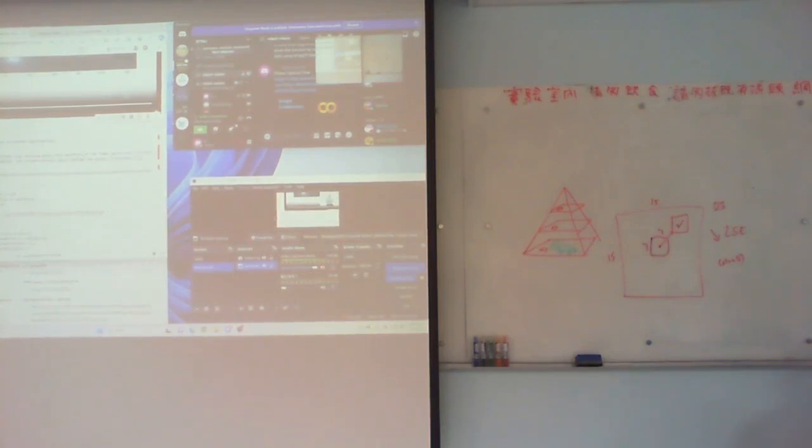You can also do sanity checks. If it's a moving robot and that point just moved 100 kilometers per hour, if it just jumped hundreds of pixels, then probably something is wrong in the tracking. So you may decide to throw that point away. Your optical flow algorithm may decide to throw that point away. You can do that by back projecting, because you cannot look into the future, but you can certainly look backwards.